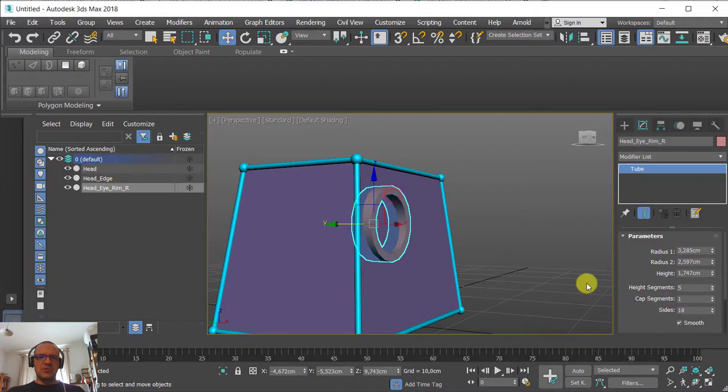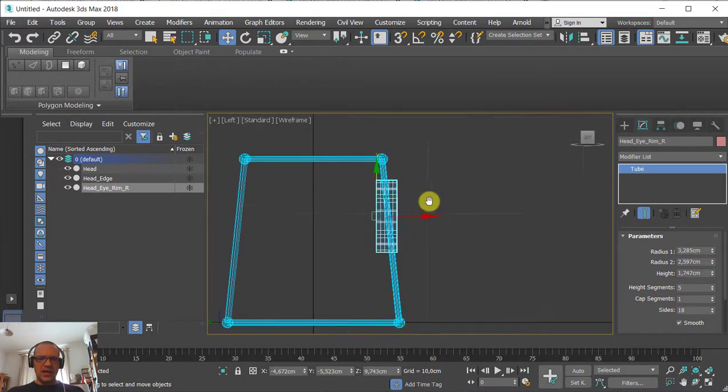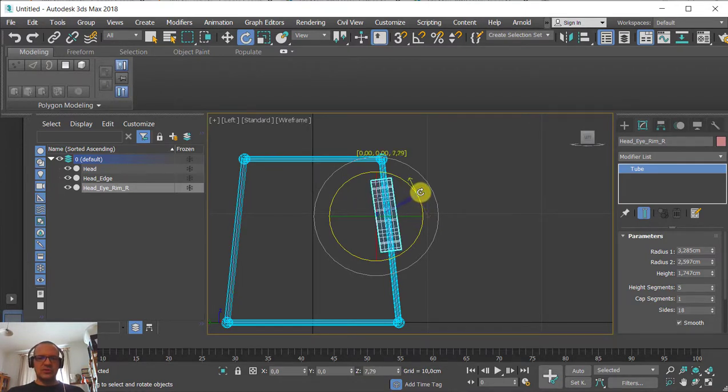So if I want to correct my angle, I can go to left view by pressing L, as in the left view, and I know already how to switch to rotation mode, so I will switch to E, rotation, and carefully selecting this, the yellow highlighted angle axis, to tilt.